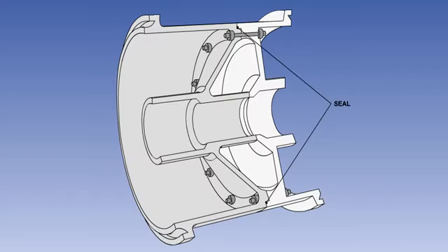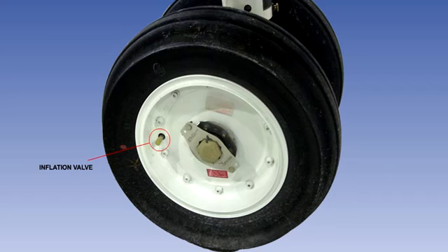Wheels for tubeless tyres are similar in construction to those for tyres fitted with inner tubes, but are ground to a finer finish and impregnated with Bakelite to seal the material. Seals are used between the parts of the wheel to prevent leakage. Unlike wheels for tyres fitted with tubes, the valve is fitted into the wheel itself and is thus not affected by creep.